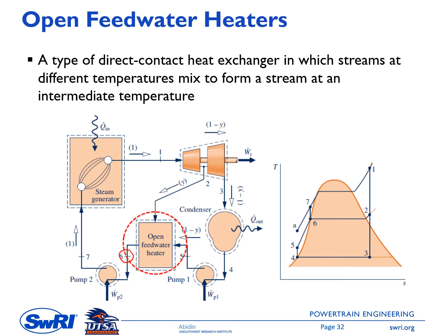Okay, let's take a look at this schematic. In a regenerative Rankine cycle, some of the working fluid is extracted at an intermediate pressure between the turbine inflow pressure and the last turbine outflow pressure. It is at pressure number 2 here.